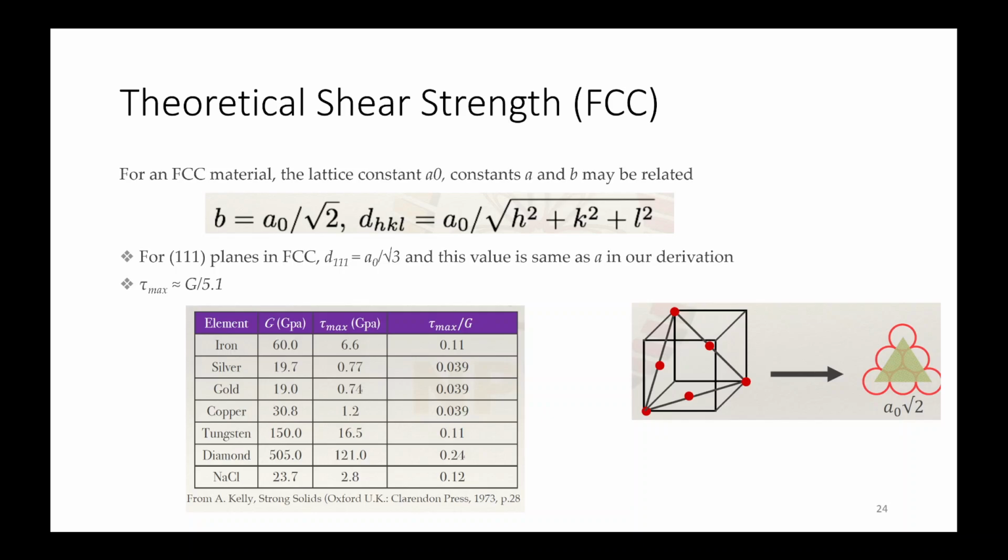For that you can use TEM, transmission electron microscopy. By that you can tell how many dislocations are present in your thin material, but there are a lot of restrictions, like your material should be a very thin plate. So for a random material sitting beside you, you can't tell it.